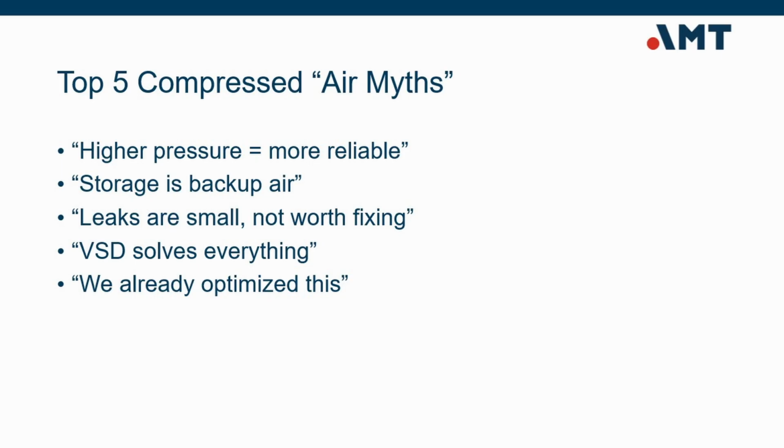Myth number 5, we already optimized this. Compressed air systems change over time. Production shifts. Equipment is added. Leaks develop. Set points creep upward. Optimization is not permanent. It requires monitoring and reassessment.